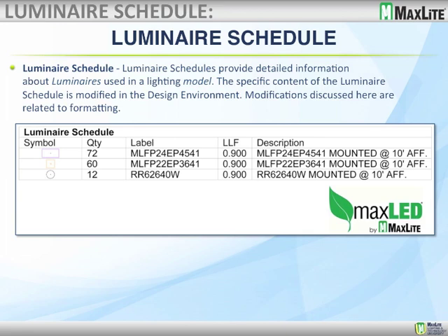The hallway is going to be about 20-foot candles average, just to get a path for walking through. But that shows you the different fixtures that we've used in this project. So when we look at that layout, we're going to see 3 different symbols, which would represent the 3 different fixtures that you've just described, and where they lie on that layout. Yes. That's an excellent explanation.